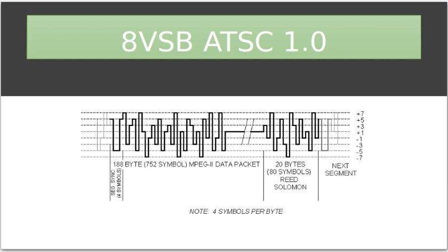And then the job of the receiver, which is always the difficult part, is to detect all those 8 levels, and based on the 8 levels, determine the bit level. Now, that all sounds well and good, but the reality is in a receiver, you're going to have multipath, and basically many of these time domain signals are going to come into the receiver at different delays, and it is a significant problem for the receiver to fix.